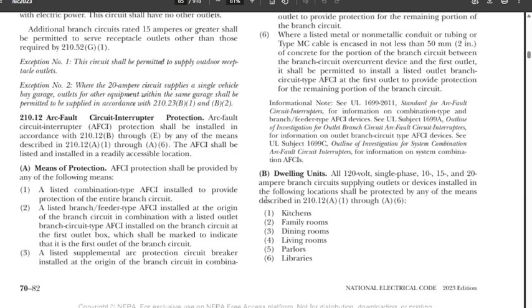And here's the thing about AFCIs. Everywhere. Where do you use AFCIs? Everywhere where GFCIs aren't required. Right? Everywhere where GFCIs aren't required. And you'll notice kitchens, which GFCIs are required in kitchens. AFCIs are also required in kitchens.